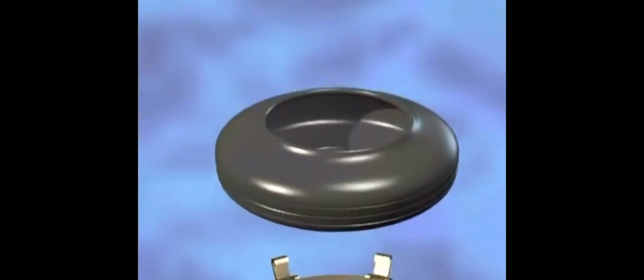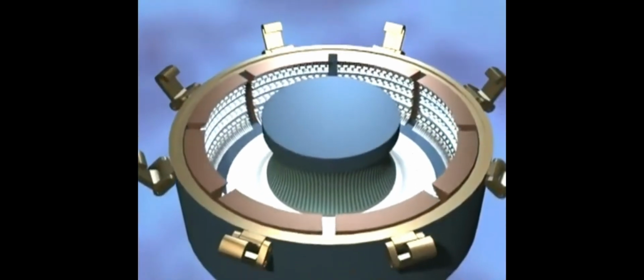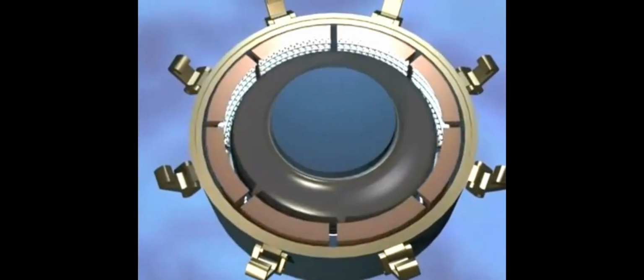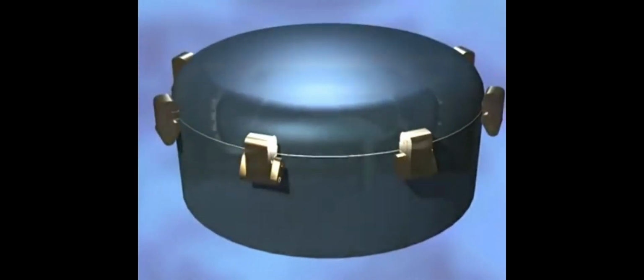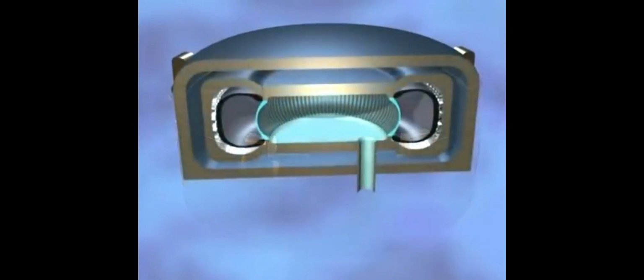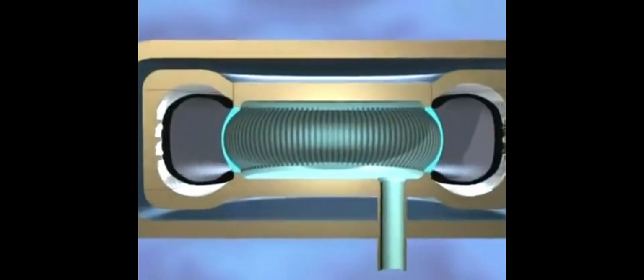The unfinished tire is then put into the curing mold, which has all the tire markings and the tread pattern. A curing bladder filled with hot pressurized water forces the rubber back into the mold cavities. The hot water and steam around the mold start the curing process.